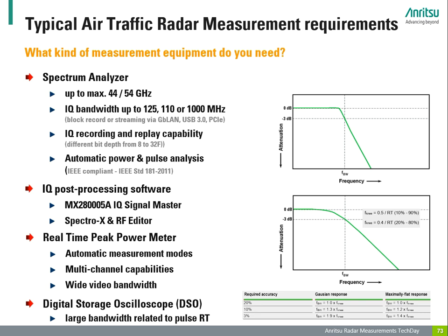The oscilloscope is always somewhere in the discussions. This is due to the much higher sampling rates and very long sampling memory. Nowadays, operation bandwidths up to 110 GHz are available, but these devices are usually very expensive. These devices are not the right tool for maintenance and repair of radars and radar signals. I'm mentioning oscilloscopes just to complete the view on this topic.